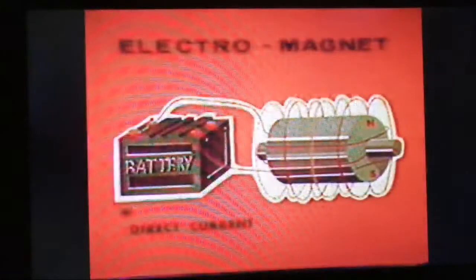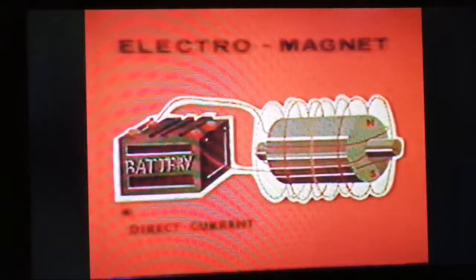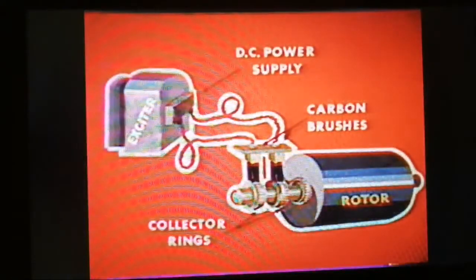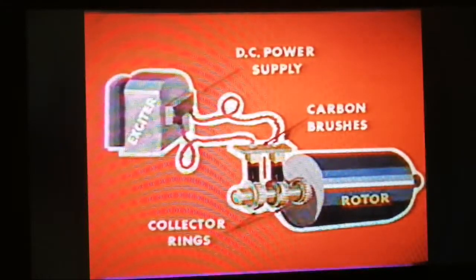In a prior film, you learned that to achieve the strength of flux and magnetic fields, the AC generator was designed with electromagnetic poles created by an excitation voltage of direct current, which was supplied to the rotating coils through a system of collector rings and carbon brushes mounted on the rotor shaft. The source of DC power was called the exciter, and although the exciter is not actually a part of the AC generator, it is so important to the control and proper operation of the generator that it must be studied as part of AC generators.